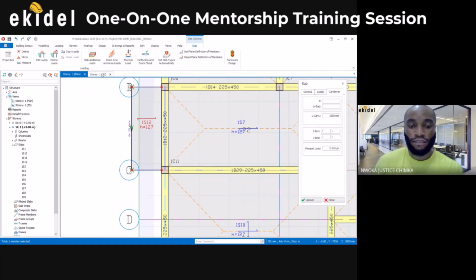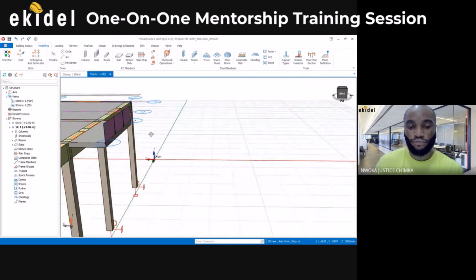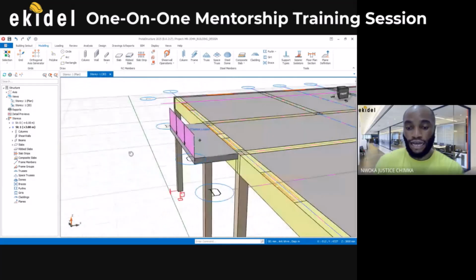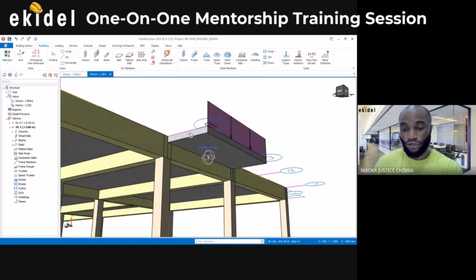If I now go to my 3D view, you can see the cantilever here and the slab showing. So you got the load showing. It already places the load. Exactly, yeah. If you also hover your hand over it, you can see load G is 3.5 per meter square, under the list of this line load that is showing. Exactly. The load is showing there.